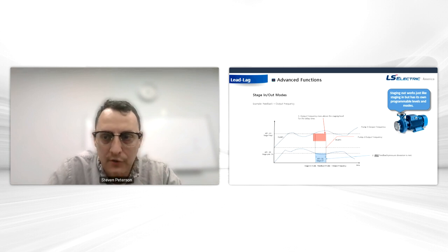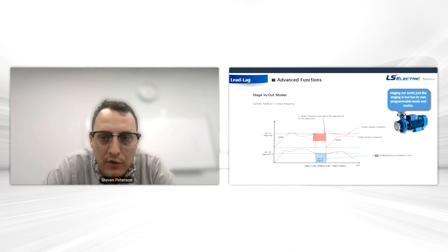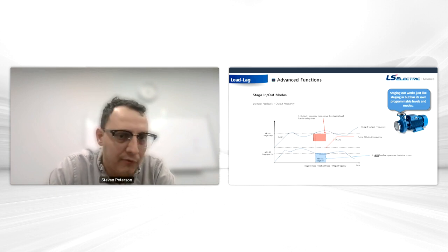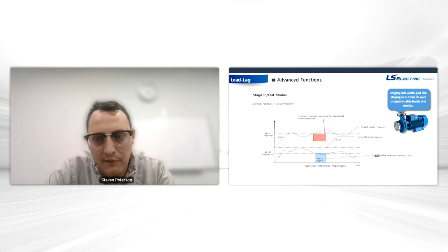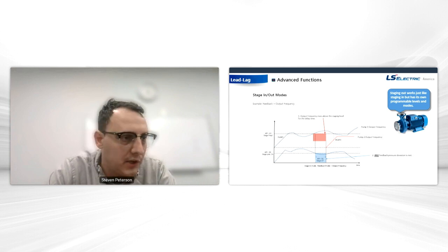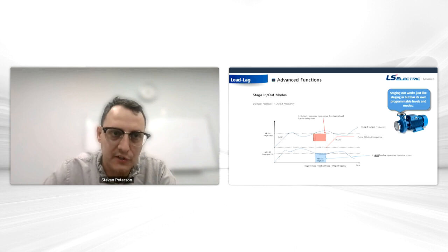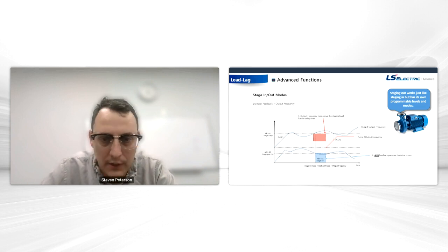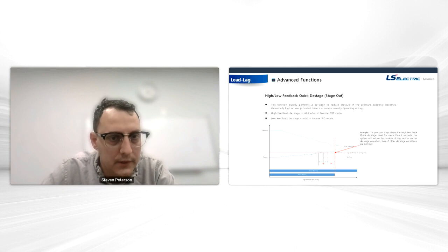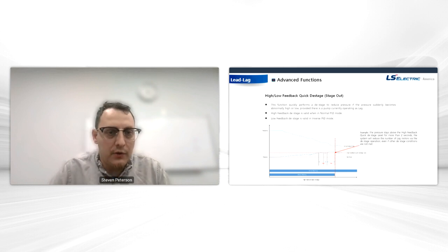And just as we mentioned right here is staging out. That works just like staging in, but obviously it's the opposite, and it actually does have its own programmable levels and modes. So you could have stage in based on frequency, and you could have stage out based on feedback. It's all customizable for whatever your needs may be. So there's a lot of parameters that you could put in there.